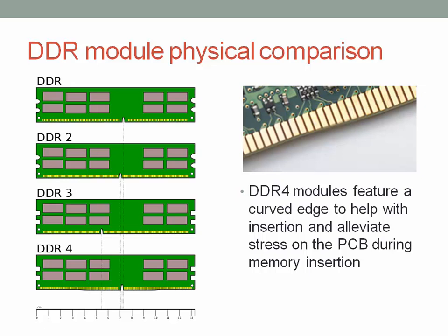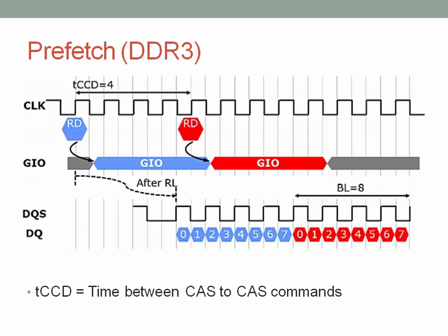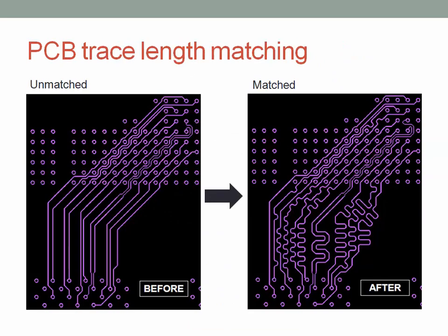On the PCB tracing, the purple PCB tracing, that side of it. So you're trying to do the matching, right? So that's going to increase delay on the figure for the match, right? Yeah, it does. Is that the only way to do it, to increase delay for one of the signals? You can't speed up another signal? Yeah, I mean, you cannot shorten the longest trace, right? So you have to make everything else longer, same as that. It makes the meandering pattern so that the lengths are the same, right? Top left one is not modified. That's the longest one.